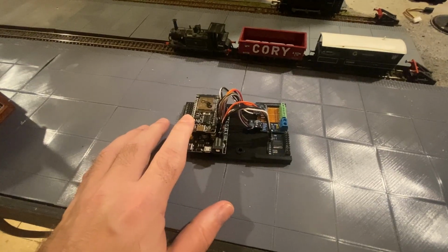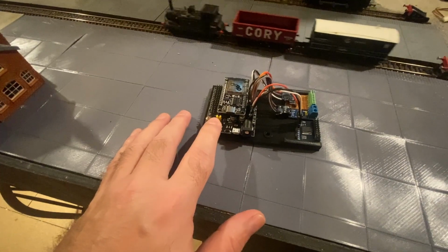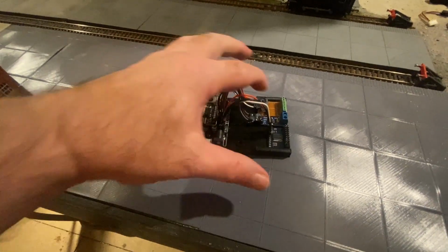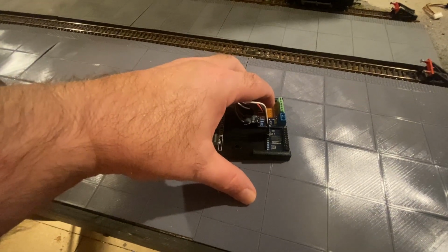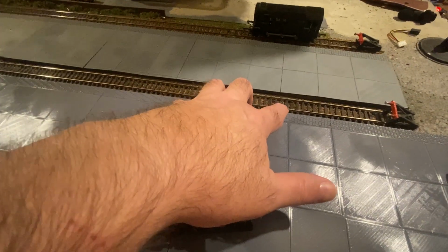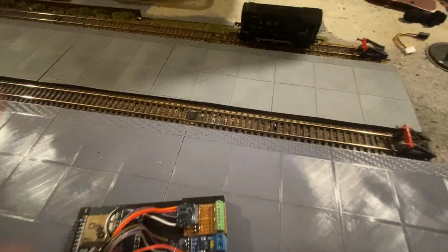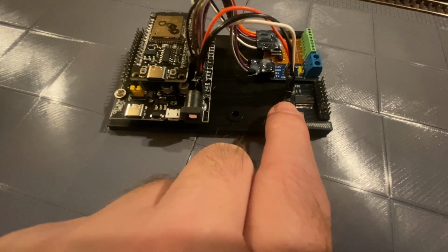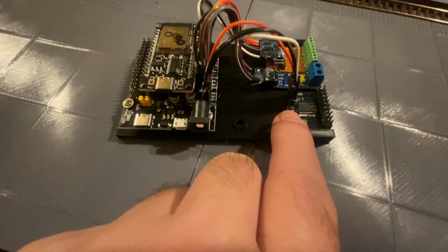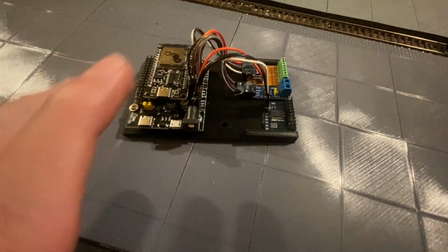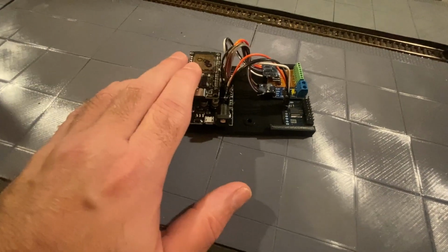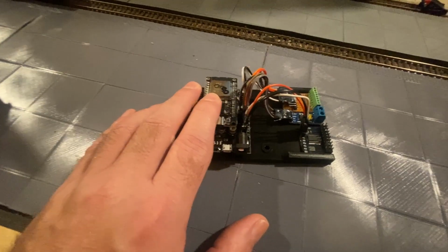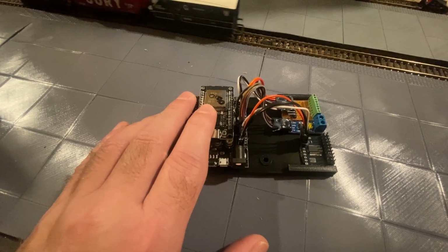And then here you can see one of my nodes. So it's the ESP32 DevKit 1 on the shield. Here you can see the small transceiver unit. This here is used for breaking out the inputs, which are used for the small block spot detectors, which you can see in the track here. And then this one here is the MCP23017, which is giving me 16 outputs. So, as I say, in this node here, this will drive 2 servos, 2 frog switches, and then it's got 10 inputs and 16 outputs.